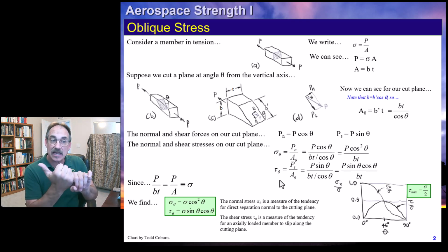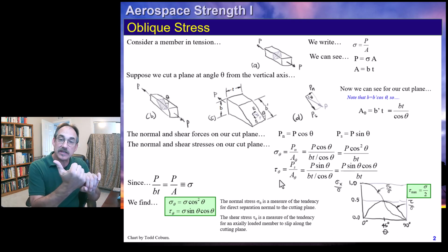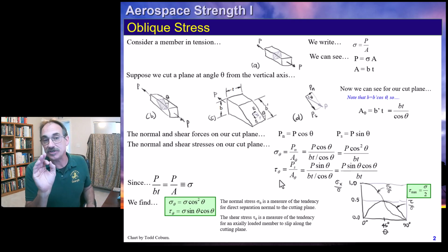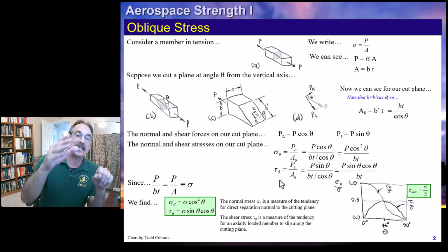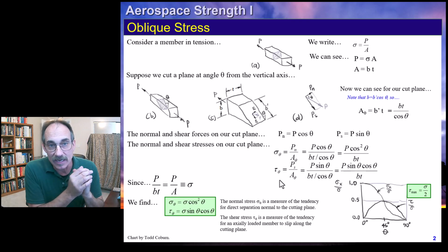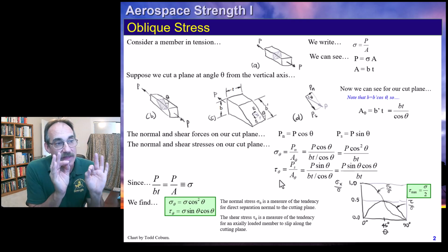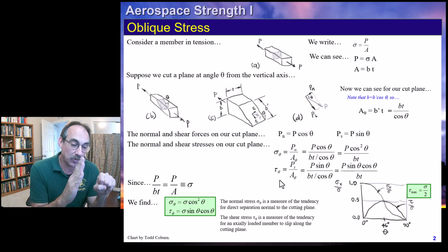But as we incline that angle, if we evaluate the stress at different angles, if we make different cuts, we're going to get more and more shear stress until we reach a maximum value of that normal stress over 2, and then it declines down to 0 again in a parabolic fashion. So that is the distribution of stresses for different cuts within the material.